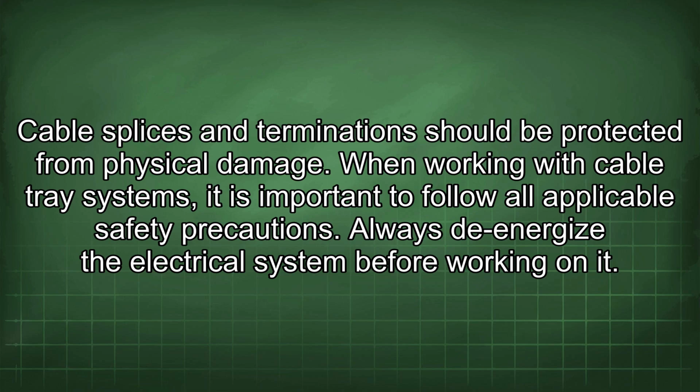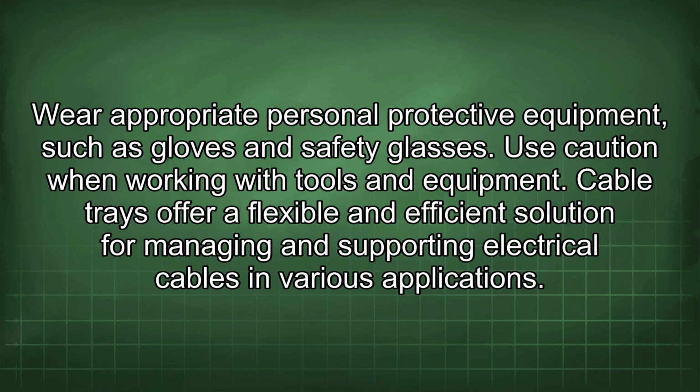When working with cable tray systems, it is important to follow all applicable safety precautions. Always de-energize the electrical system before working on it. Wear appropriate personal protective equipment, such as gloves and safety glasses. Use caution when working with tools and equipment.